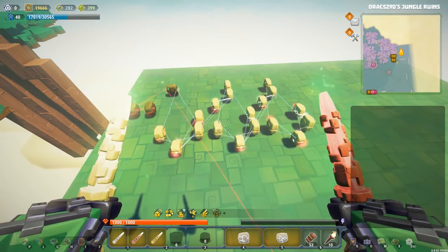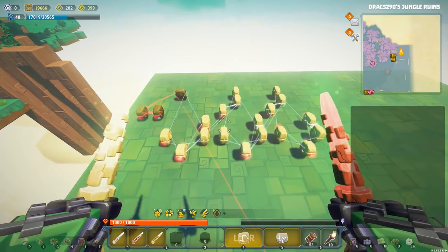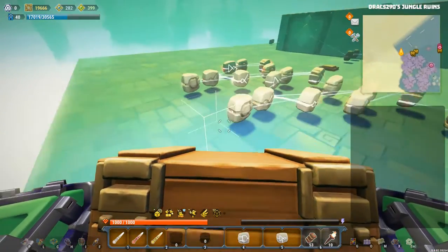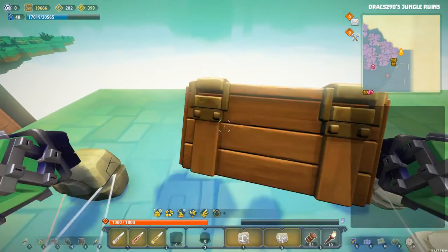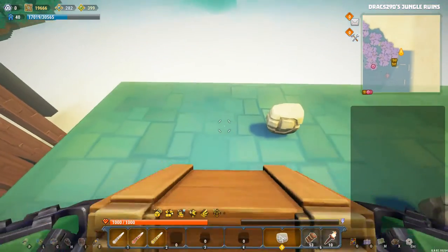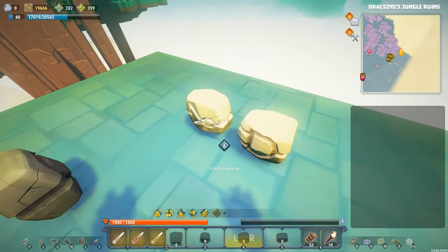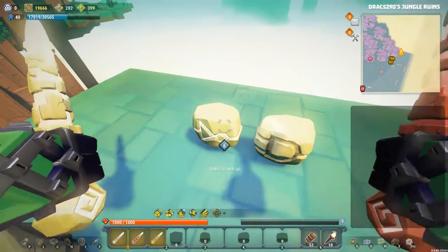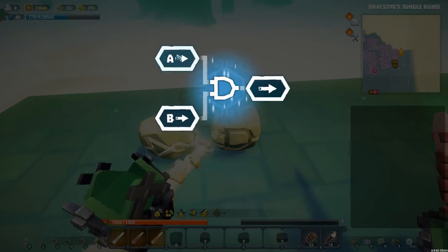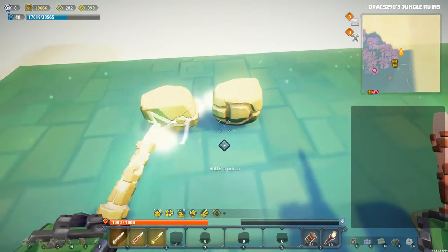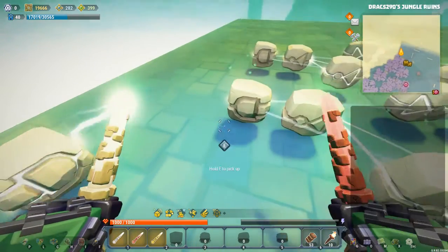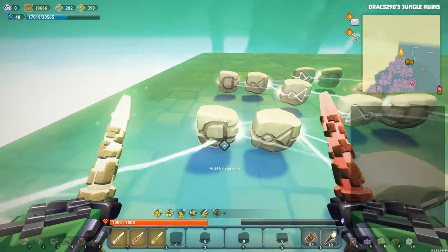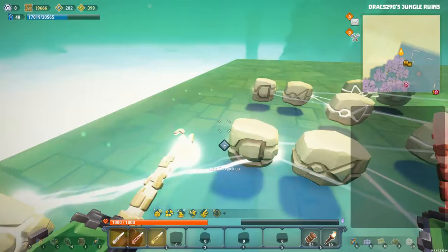So that's the first part of this, although actually I still have one NOT gate and one AND gate in my inventory because we've forgotten the protection for this guy. So we're going to place that guy down and that guy down, and we're going to run the NOT gate into both the A and the B for this AND gate, just like that. And then we're going to run this AND gate into the B side of the two falling edge AND gates that we've got over here.